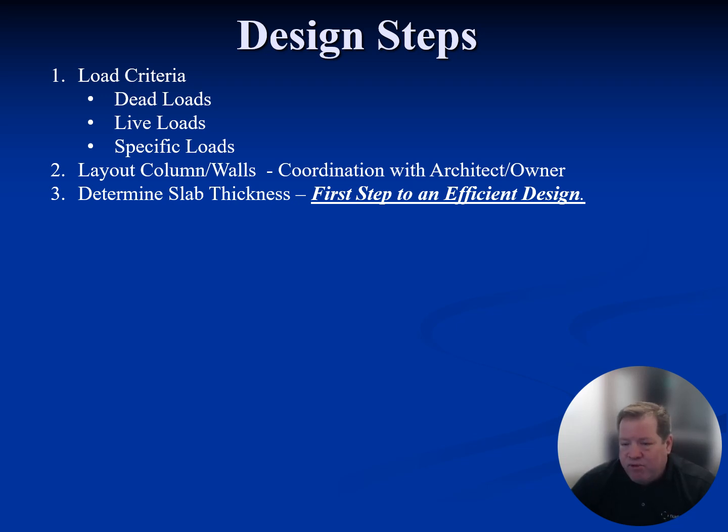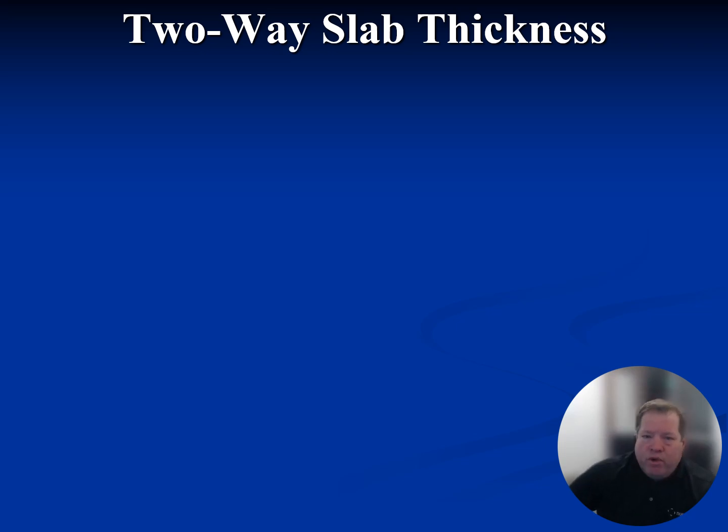As I mentioned before, we win in slab thickness. There's no reason to go thinner. We win, leave it at that. The money is saved with a reduction in rebar, not so much taking an extra inch or two out of the slab thickness. Yes, there's a seismic benefit. Yes, there's a vertical load benefit, but the amount of rebar you're going to add for PT, or the amount of reinforcing you're going to add, coupled with the punching shear issues and just the construction issues, it's not worth it. So the question is going to be, of course, how do you get the right slab thickness?